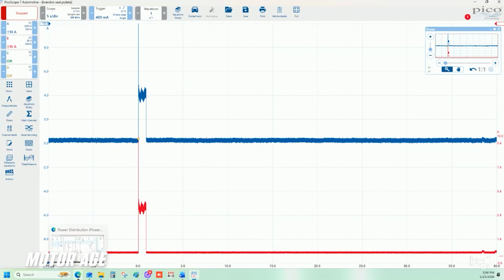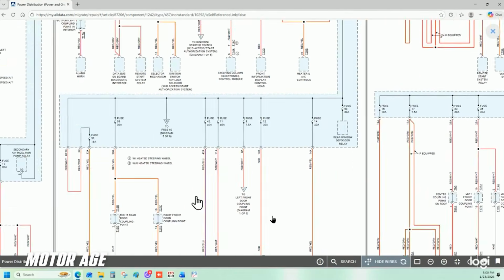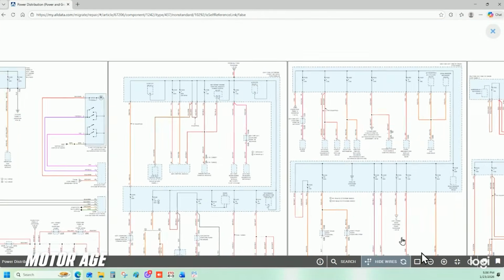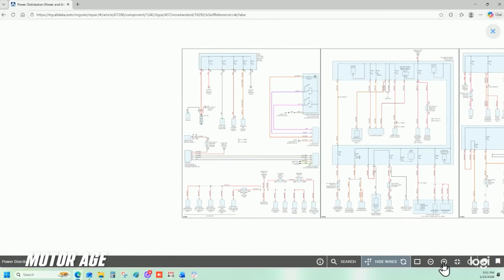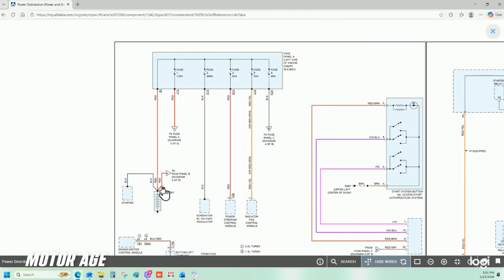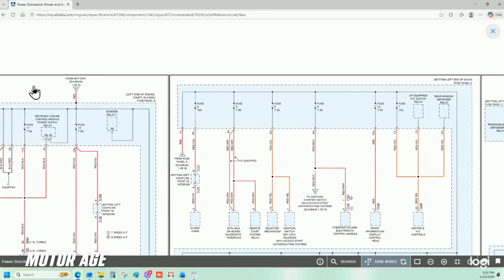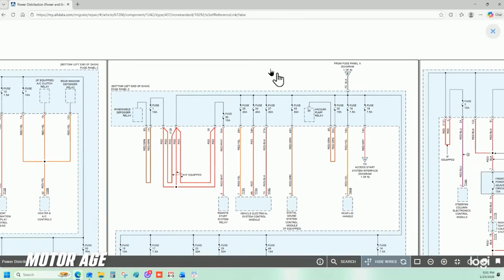And in this case, if we go back and reference our diagram, let me zoom out a little bit to make this easier to navigate. Of course, this is our battery, our source, and current flow can only go in several places: 1, 2, 3, 4, 5, and 6. We had our blue trace reference to battery output, and we had our red trace reference to fuse 4, SA4 output, which of course leads to fuse panel C on page 4. So there's page 1, 2, 3, and 4.